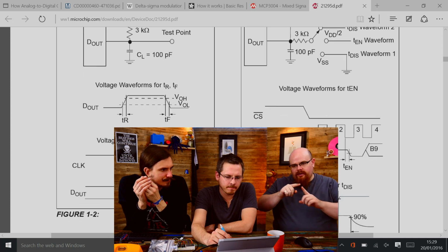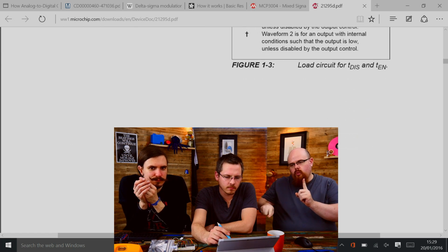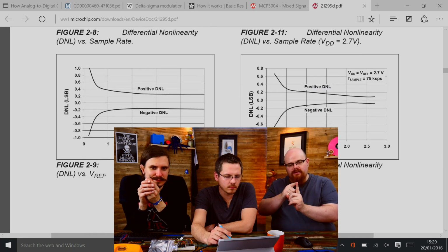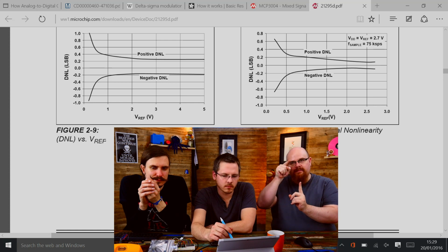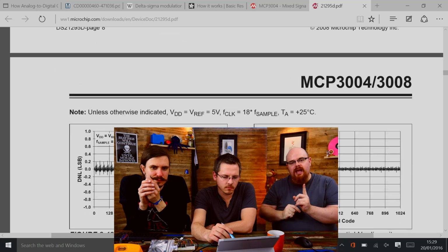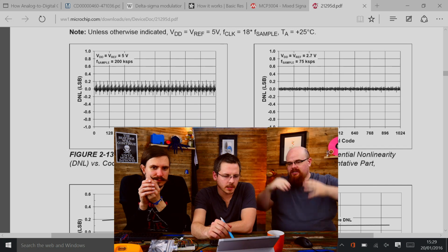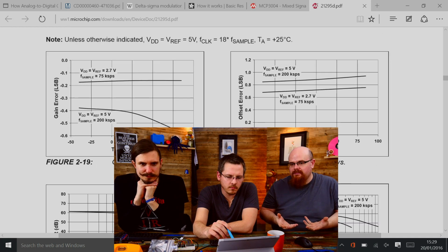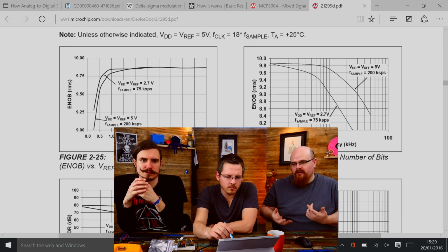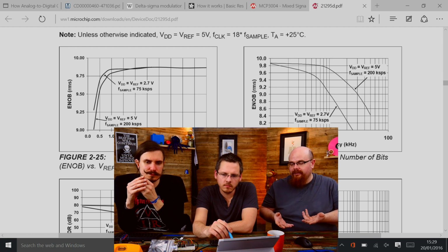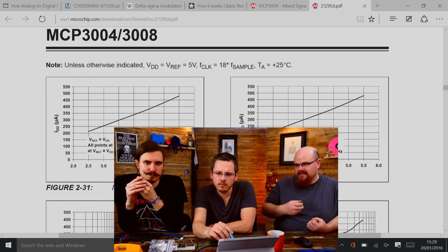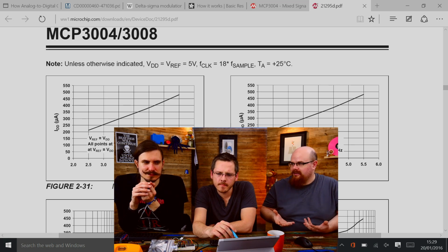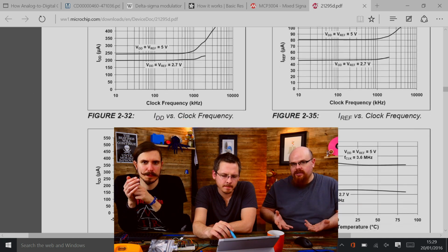So we've got the 1 hertz thing where the sine wave is going woo, woo, woo. Now if you were sampling that once per second, you could always hit it when it's going woo. So you can sample it woo, woo, woo, and you'd assume that was always at the top level, like that was always a high signal. Therefore, you're getting a really false impression of the analog thing you're sampling. So that's why you need a frequency that's suitable for the signal you're looking at. I think the high-end version of that is things like an oscilloscope, which can sample up to 1 gigasample a second. That's 1 billion samples every second.